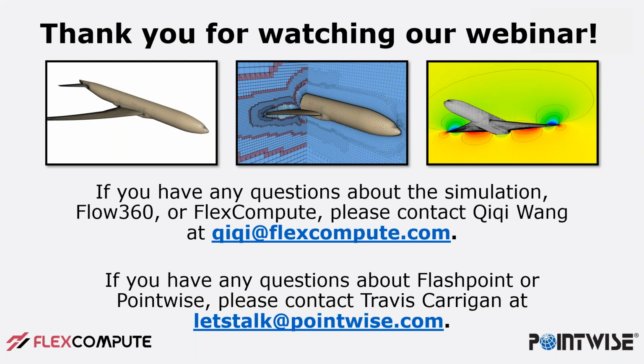Like a convex edge, you shouldn't have a quilt that wraps around a convex edge. It should end and terminate at the convex edge. Same with a wing leading edge where you've got a round, you need to have a quilt boundary there so that it can detect that there is in fact a curvature type boundary there. So long as those things are honored, then it will recover those particular features.